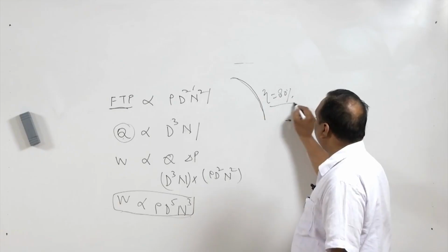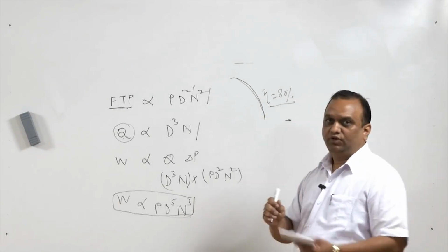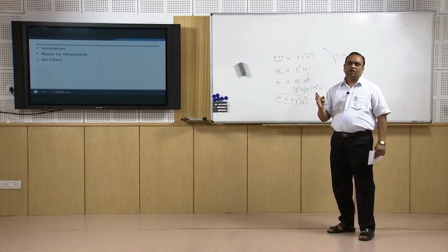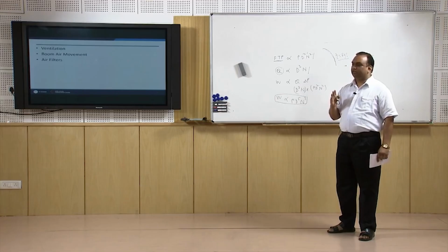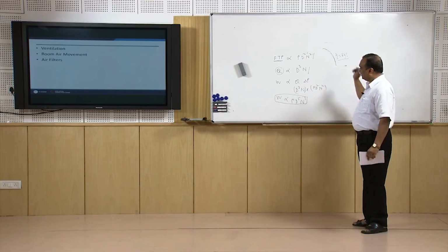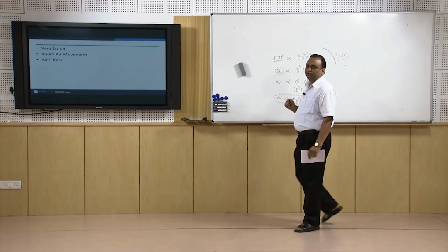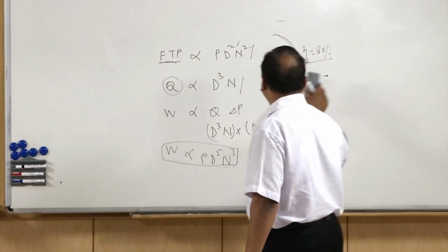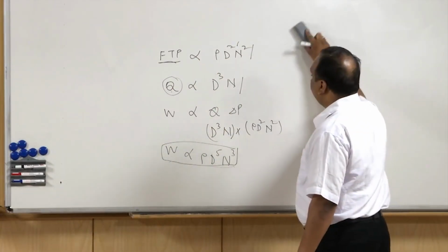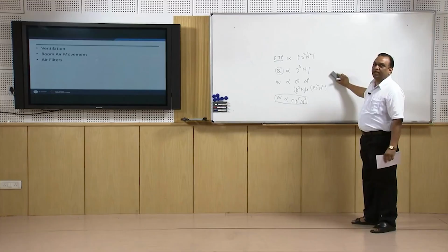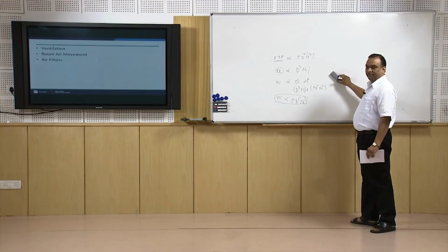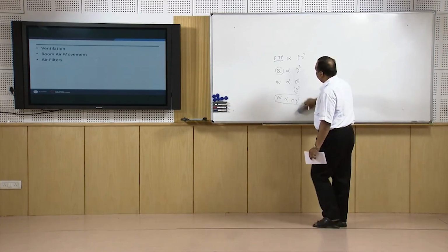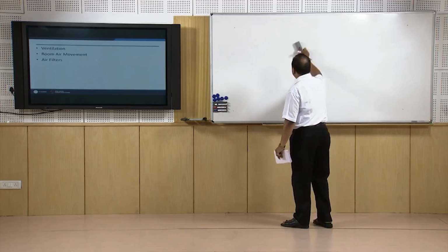So, efficiency is also high, and if you deviate from optimum design conditions, the change in other parameters is not significant. So, that is why in most cases of centrifugal fans, the backward vane type of system is used, unless a very high pressure ratio is required. If a very high pressure ratio is required, then forward vane type of fans are used.